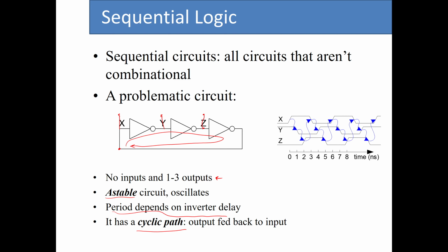We said that the D flip-flop is the most preferred state element because not only does it give us access to the time at which we want to store a data bit, or one bit of state, in the flip-flop, but there was also a separation between the time that we stored the data and the data that we wanted to store. And finally, that process of storing the state would happen practically at an instant.